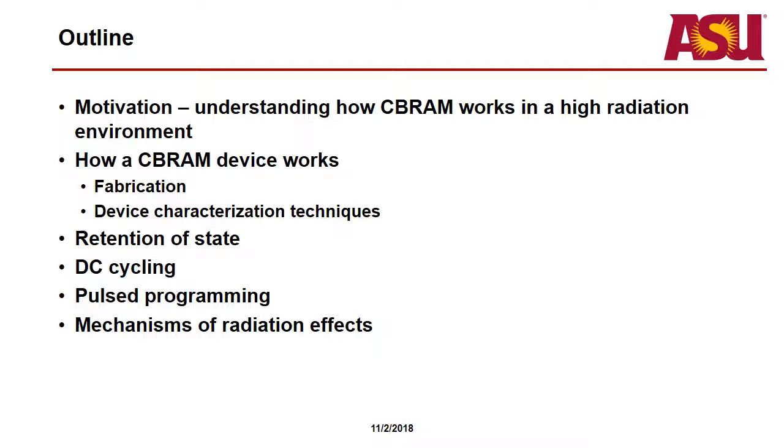So the motivation for my work is to understand how these CB-RAM devices work in a high radiation environment, such as you might find around Jupiter and its moons. As far as NASA is concerned, one of their upcoming missions is the Europa Clipper mission. The electronics within the satellite are going to have to withstand a very high and intense radiation environment, and need to withstand 10 megarad or above of exposure to high energy electrons. I'll get a little bit more into that after this slide.